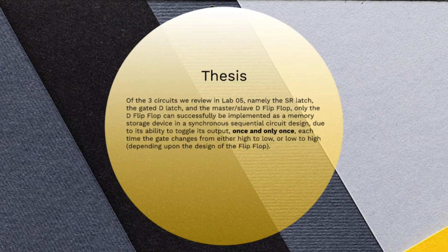In Lab 5, we studied the characteristics and limitations of the simple SR latch, the improved design gated D latch, and finally the master-slave D flip-flop built from two gated D latches. Due to the inherent limitations of the SR latch and gated D latch, only the master-slave D flip-flop can successfully be implemented as a memory storage device in a synchronous sequential circuit design. This is because the master-slave D flip-flop toggles its output once, and only once, each time the gate changes from either high to low or low to high, depending on the design of the flip-flop.